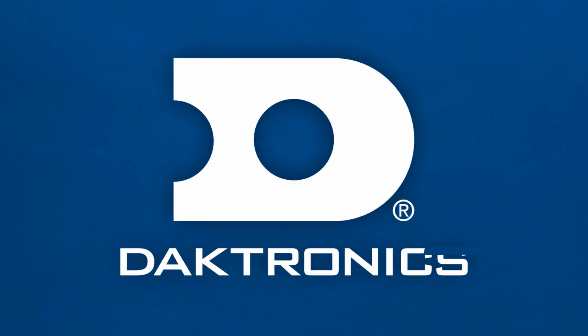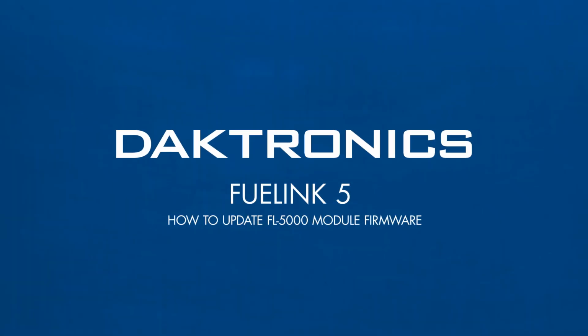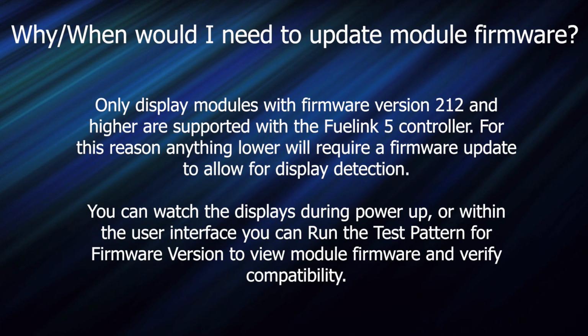In this video, we are going to cover how to update the module firmware for the FL5000 display, starting with why and when you would need to update this module firmware. Only display modules with firmware version 2.12 and higher are supported with the FUELINK5 controller. For this reason, anything lower will require a firmware update to allow for display detection.